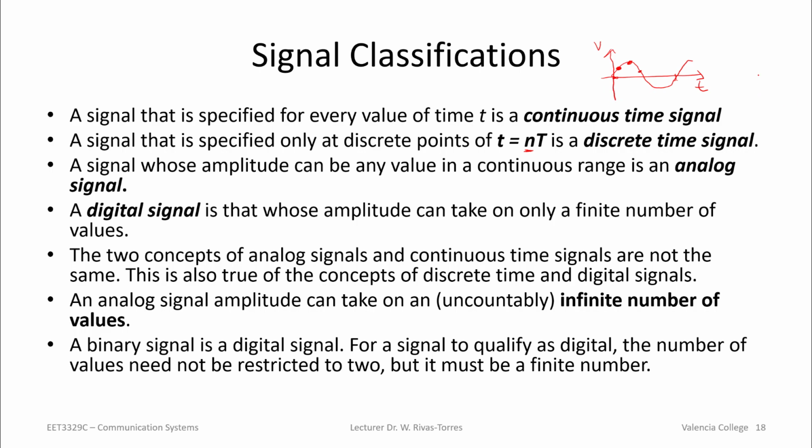So when I end up looking at my discrete signal, what I have is a series of dots, let's say dots for now. And that's what your discrete signal looks like. You do not have values in between. So if my sampling time is 1 second, I know my signal at 0, I know my signal at 1 and at 2. What happens in between, I don't keep that information, right? I can probably make inferences as to what the values are, but I don't keep those values.